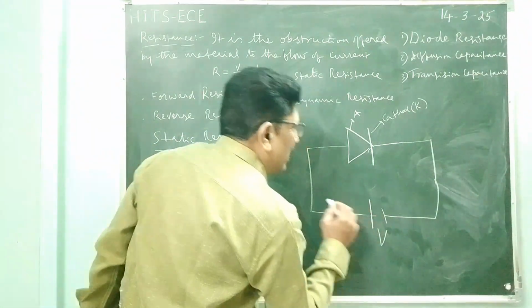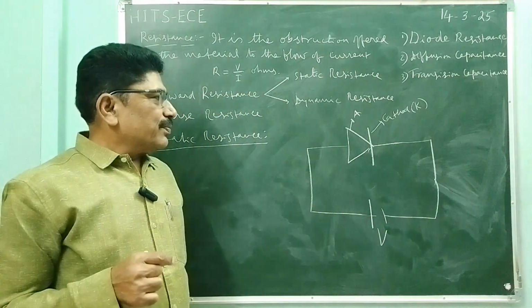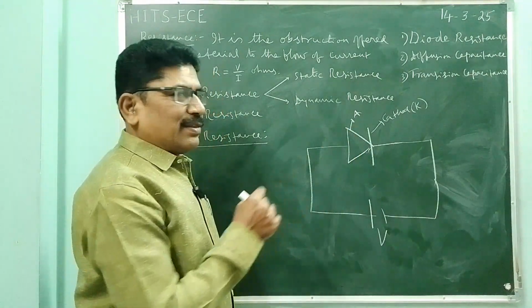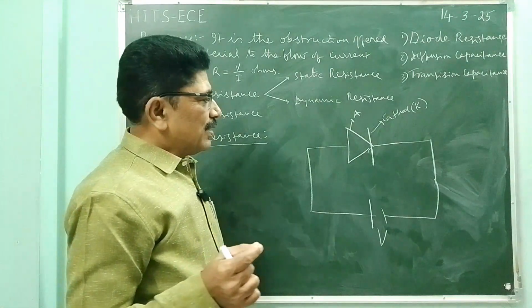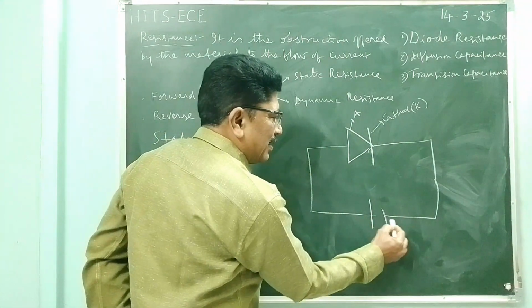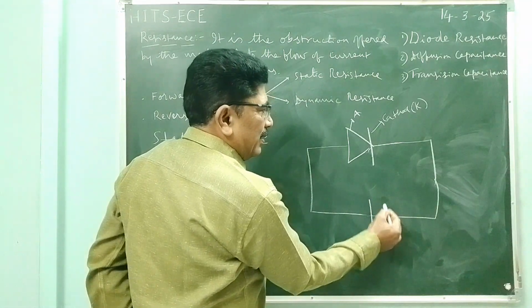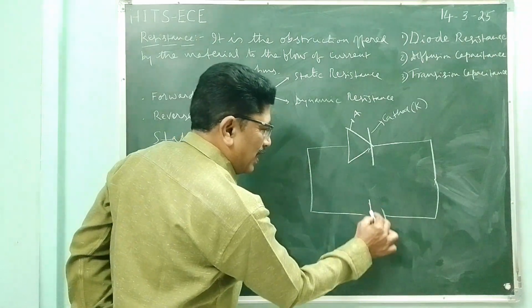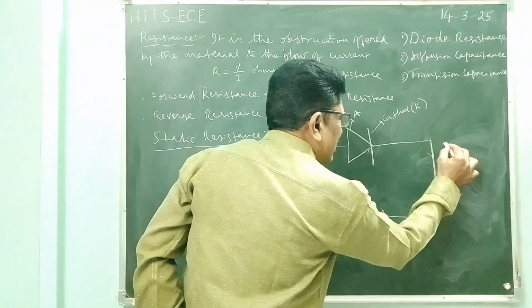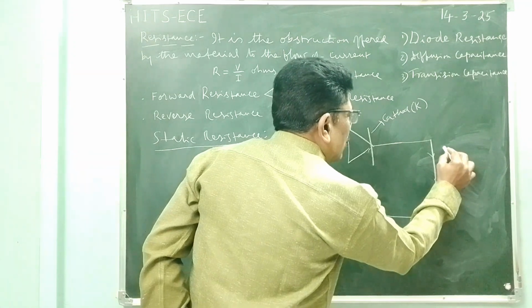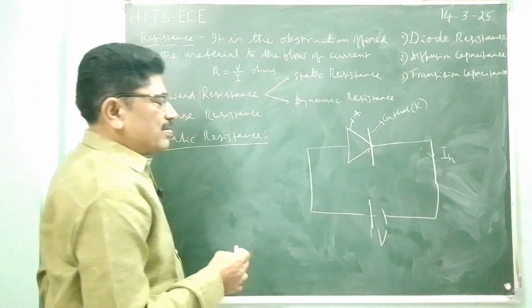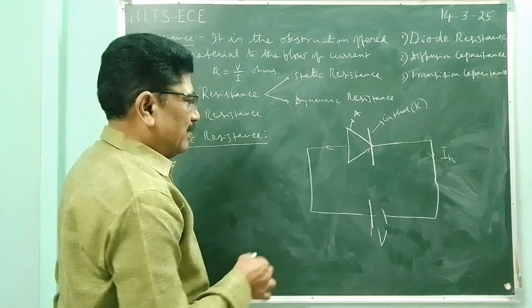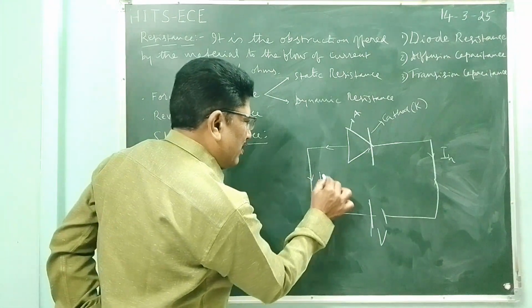So this is the voltage applied across the diode. This is the forward bias condition. So how will the current flow? The anode will have holes and the cathode will have majority carriers, electrons. The electrons will be attracted by the positive polarity, and the holes will be repelled by this positive polarity. So the holes will move like this. Let the current due to holes be IH. The electrons will be repelled by this negative charge and will cross the junction. So the electron current will be IE.